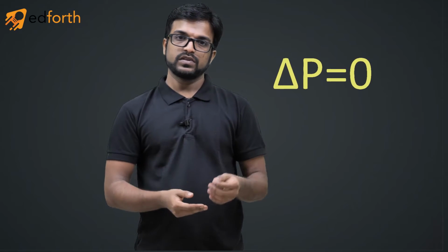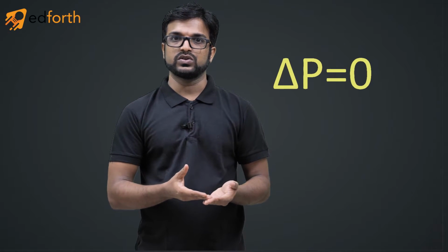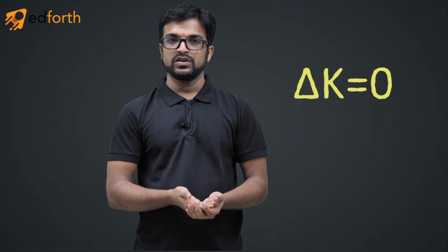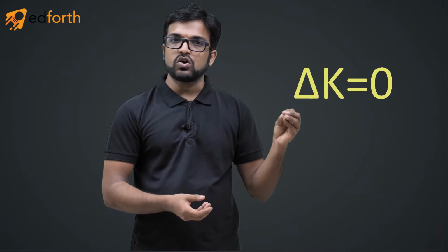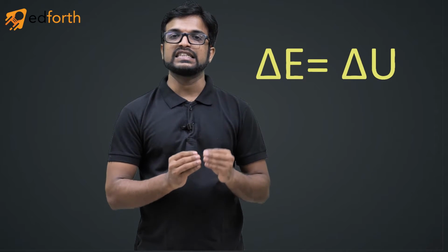Now you can see that in general, when I am doing some experiment on my system, like when we are doing the experiment on my water bottle, it will be stationary. As a result, its initial and final potential energies are the same. So what is the change? Zero. Same goes for my kinetic energy also. Change in kinetic energy will be zero. So finally I will get that change in total stored energy is equal to change in internal energy, provided I can neglect change in kinetic energy and potential energy.